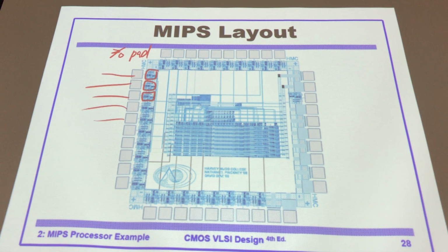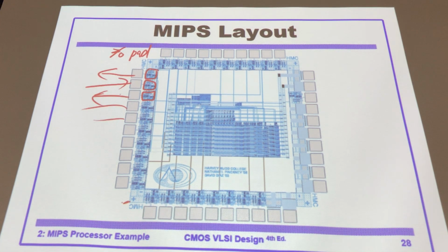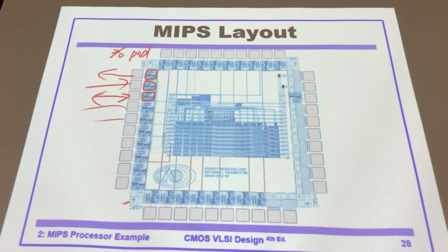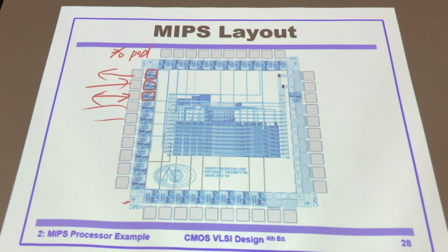So before you drive the signal, either 0 or 1, you need to go through an analog circuit that can provide very large driving capability to drive the signal onto the circuit on the board. And likewise, when you receive a signal from the outside, it could be output, could be input, could be bidirectional. Each one needs an I/O pad circuit that can provide the required signal strength going out or getting in. So you can view it as some kind of interface circuit.